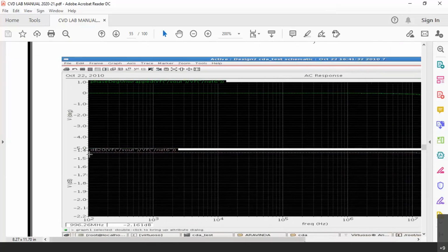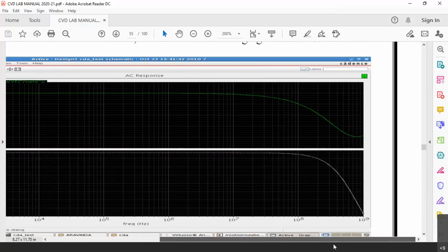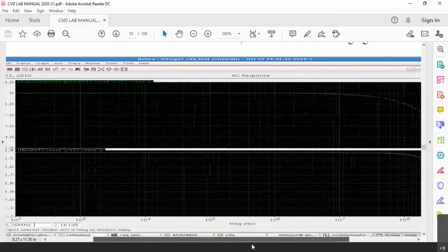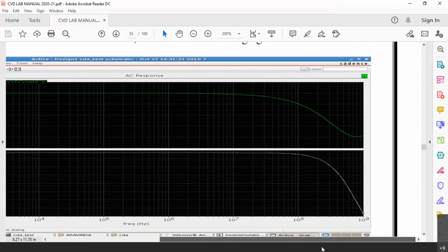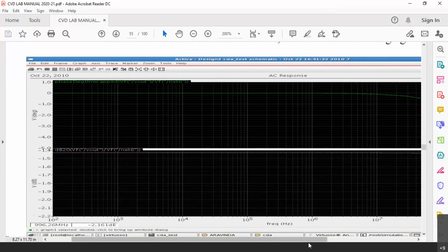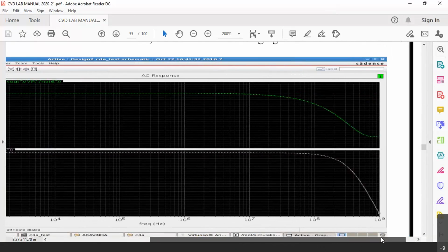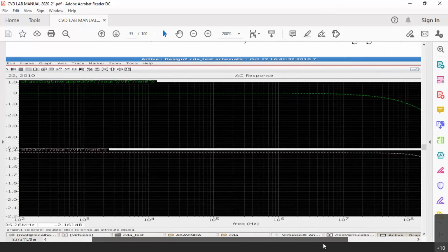We have to go to minus 1.4 minus 3, which is minus 4.4. Of course, in this screenshot that is not shown, but when you conduct the experiment, when the offline labs start, you can observe that if you keep increasing the frequency here, at what point you will get minus 4.4 as the upper cutoff frequency, and that will be the bandwidth of this amplifier.